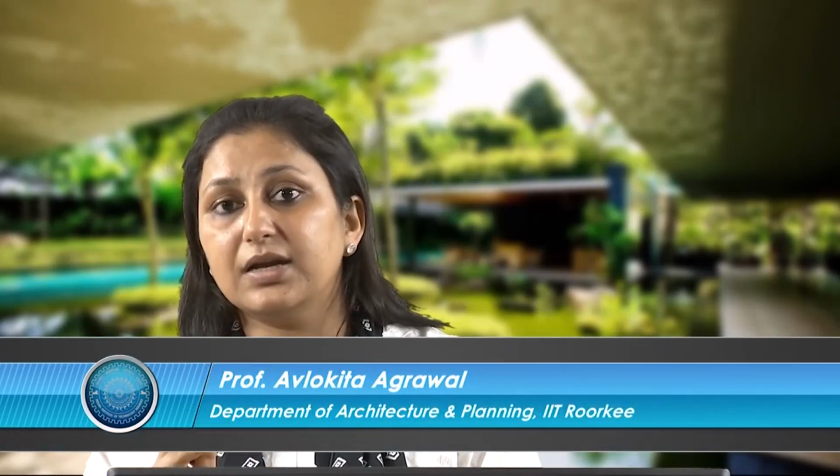For convection, we use features such as jali. The hot air, because it will be passing through these small holes, pores, will lose its heat and cool down by the time it is transferred to indoors. For radiation, we provide shading devices, we provide jharokas, we provide chhajjas, we provide overhangs, so that the direct radiation is cut off. So, these fundamentals of heat exchange are important to understand, because then we can design the buildings appropriately for the given climate and for the given context in which we are working.